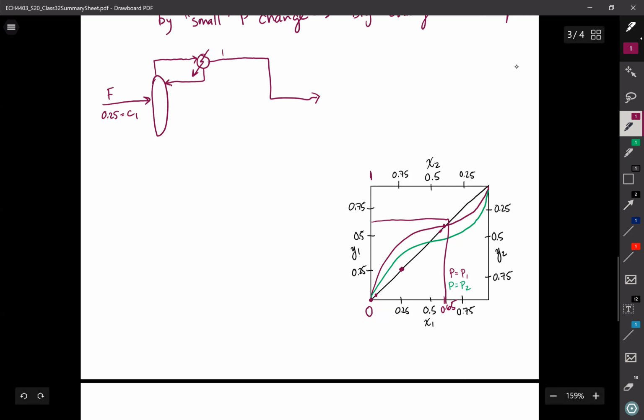So this is going to be distillate product 1, slash the feed to column 2. That'll be a little bit later. We're going to take the distillate product and feed it to the second column. As I said before, this column is operating at pressure 1, and we'll say that the composition of this stream is nearly azeotropic for pressure 1.